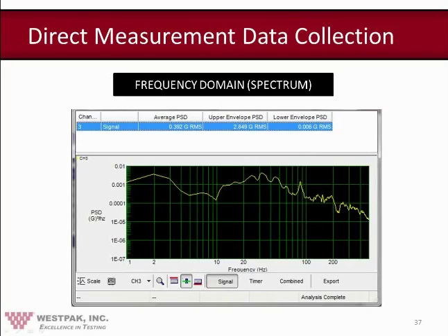So this is the overall GRMS level, which is shown at the very top, 0.39 approximately. That gives you the mean or average amplitude of that line. But that's also the area under that acceleration versus time pulse, or the root mean squared area. So this is the preferred format, and you can see why it's so handy, because you can actually quantify it using this particular method, whereas in the time domain you really can't. It's almost impossible.